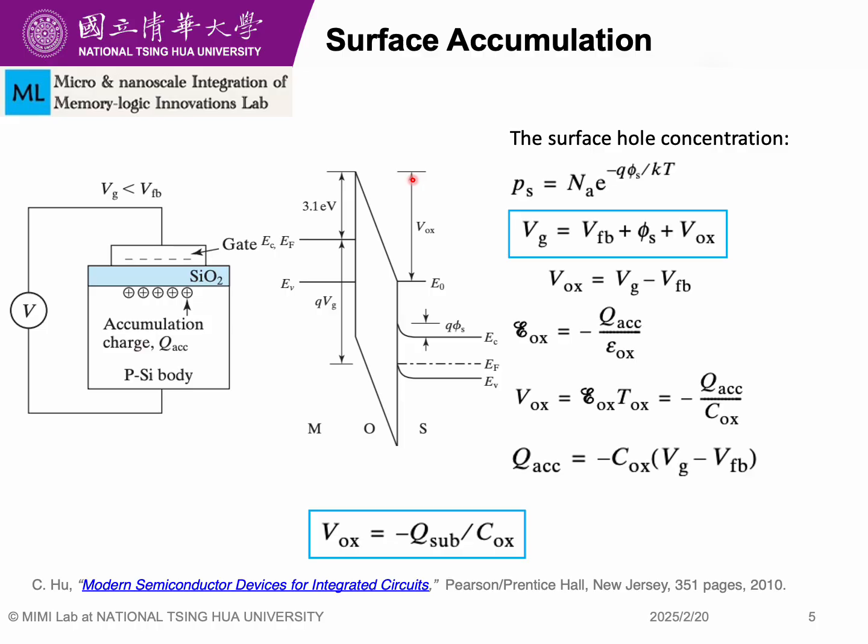And the band bending is upwards because the voltage is negative on the gate, for p type or n type, whatever it is. I mean, if you apply negative voltage, it will go upward. Now if my EC is going upward, that means my surface voltage is also negative, and it will be positive if it bends downward. However, here it is negative as we applied the negative voltage.